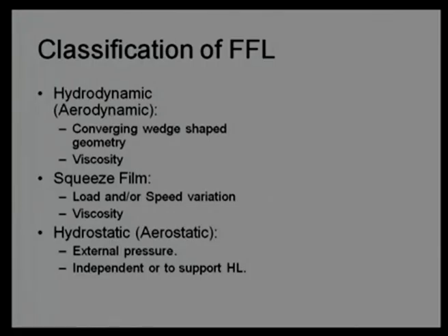Second mechanism is a squeeze film. This is basically governed by speed variation, and speed variation in direction of film thickness or changing the magnitude of the load or changing the direction of the load. There should be some sort of variation which brings squeeze film into action, or this mechanism will be accounted only when we have a load variation or speed variation. Viscosity also plays an important role in this kind of mechanism.